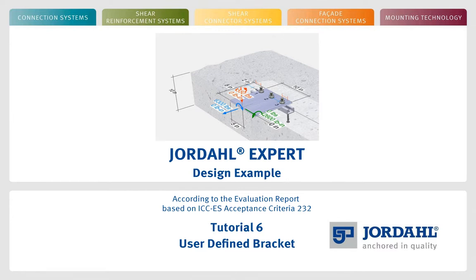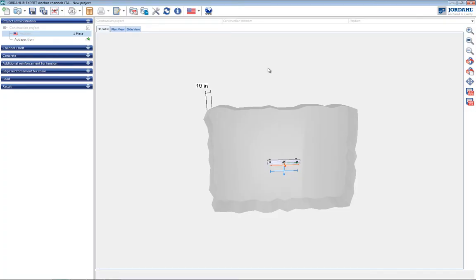I will now demonstrate to you how to use JORDAHL expert software to incorporate a specific bracket design into anchor channel connection calculations. The software provides calculations compliant with the anchor channel evaluation report based on ICC-ES Acceptance Criteria 232. The JORDAHL expert software provides default bracket geometry, but as in this example, it also allows designers to define a user-defined bracket, where forces and moments can be specified in all three directions.